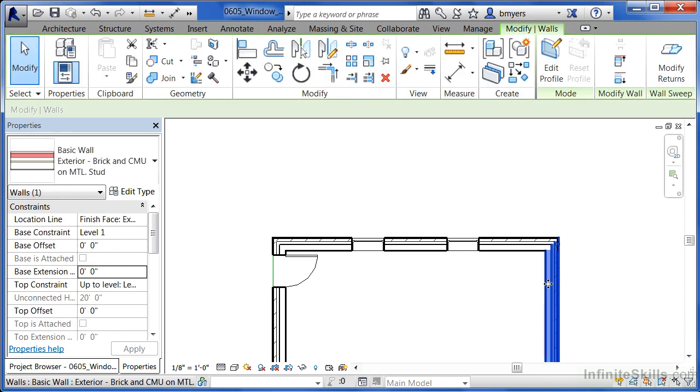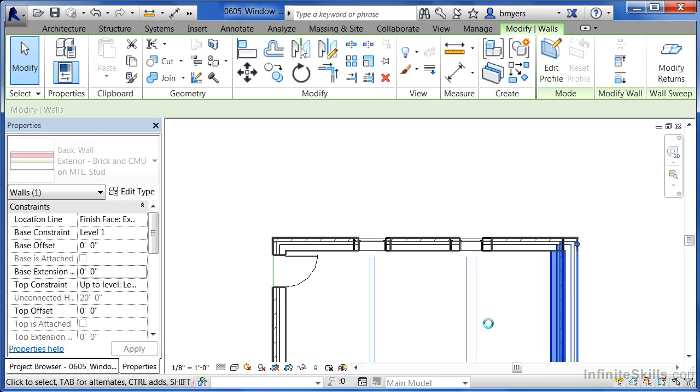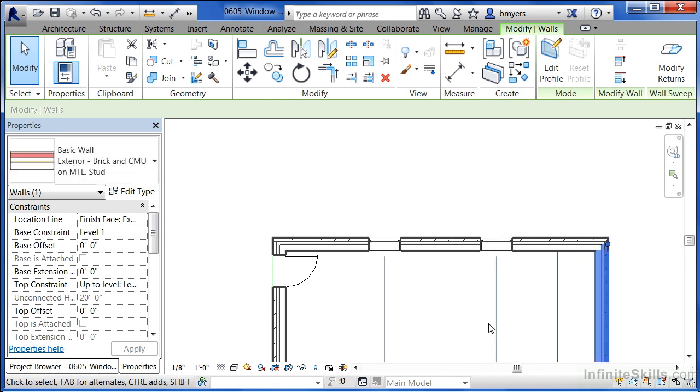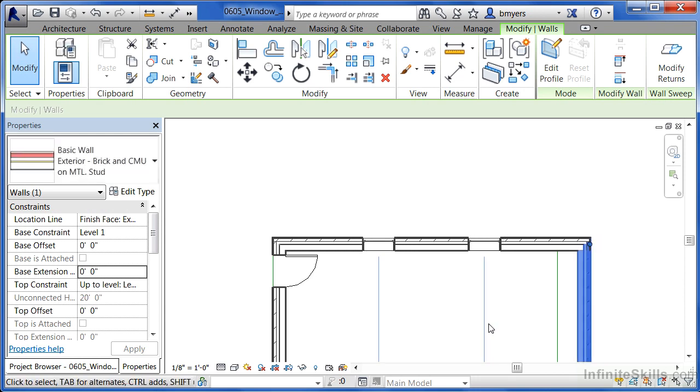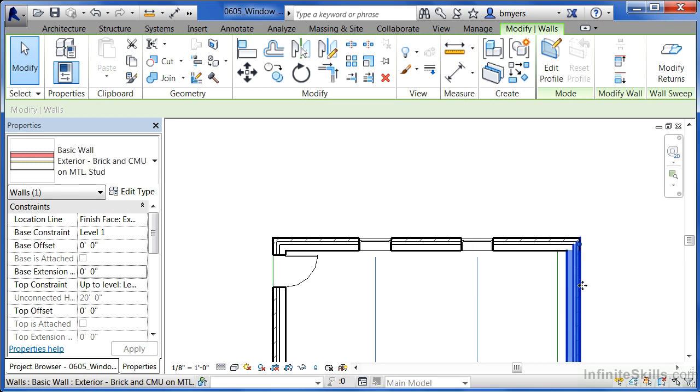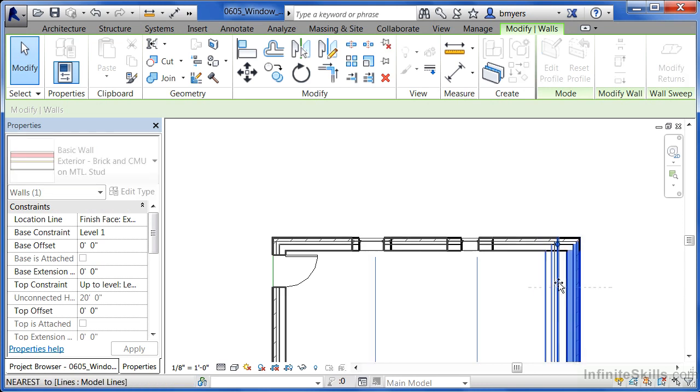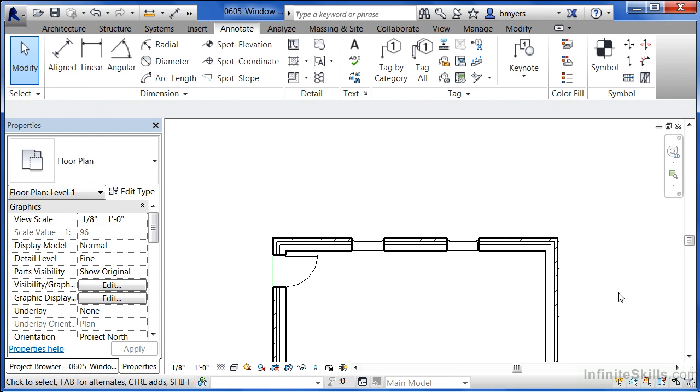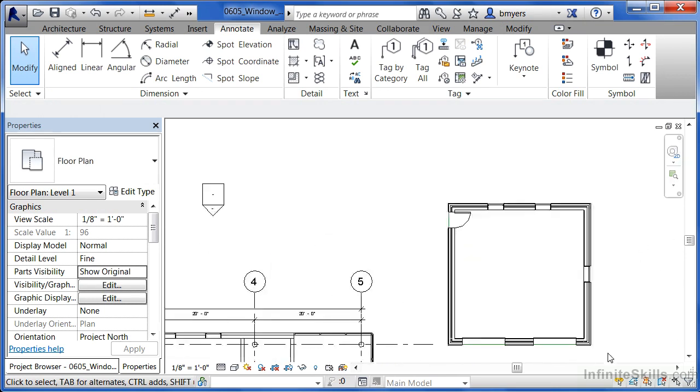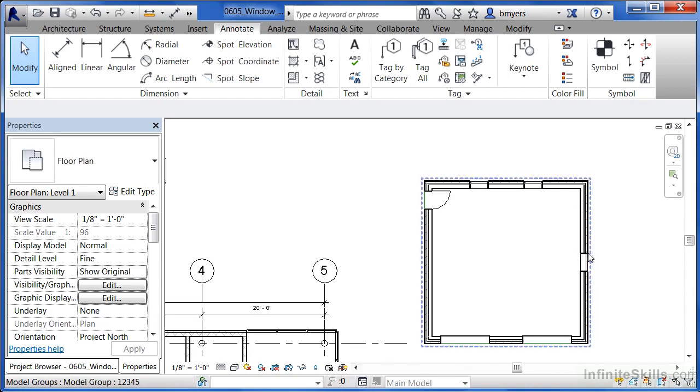What this means is if you select this outer wall here, now look at your keyboard, and click the right arrow key. If you start tapping the right arrow key, it's going to nudge that wall over to a different location. But as you nudge that wall over, the window stayed centered along whatever the length of that wall is. Go to the left again, it'll do the same thing. Now in order to get the wall back in the location that it was at, I'm going to click and hold my mouse button down along the edge, and then let go when it snaps onto that green line, and then click out into space. You'll also notice that the window that was on this wall here actually moved out with it, and it stayed locked when you moved it back in.